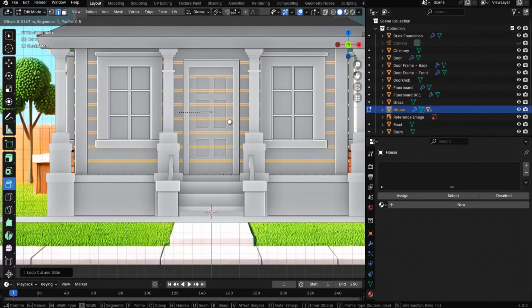All right. Before we do that, give it a mirror modifier, and let's create the roof panels for the back side. Okay. And then let's Shift D to duplicate that one more time, and we'll make the top side for essentially the top roof, and put that right there. And then we'll bring the count down on our array modifiers, and then we'll just delete whatever vertices we don't need for anything that overshoots our roof. We'll just delete those right off. And just like that, we've got a nice little roof. Okay. Let's do the same thing to create the mid-level roof, that tiny little mid-level roof.